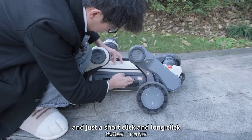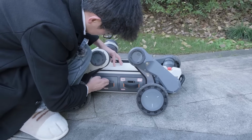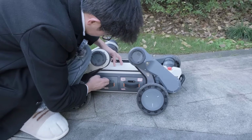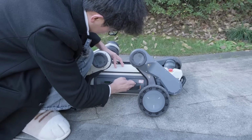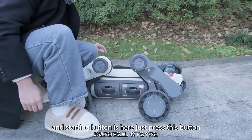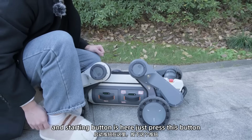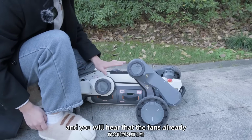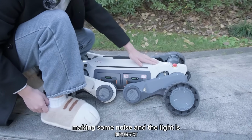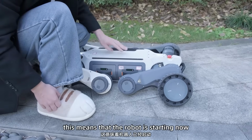And just a short click and long click. Okay, so now 2 batteries are on, and the starting button is here. Just press this button, and you will hear that the fans are already starting to rotate and it's making some noise, and the light is blinking in white. This means that the robot is starting now.